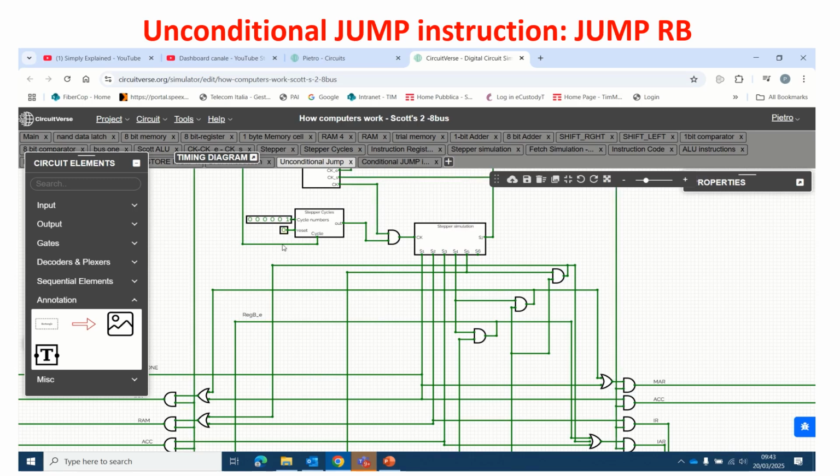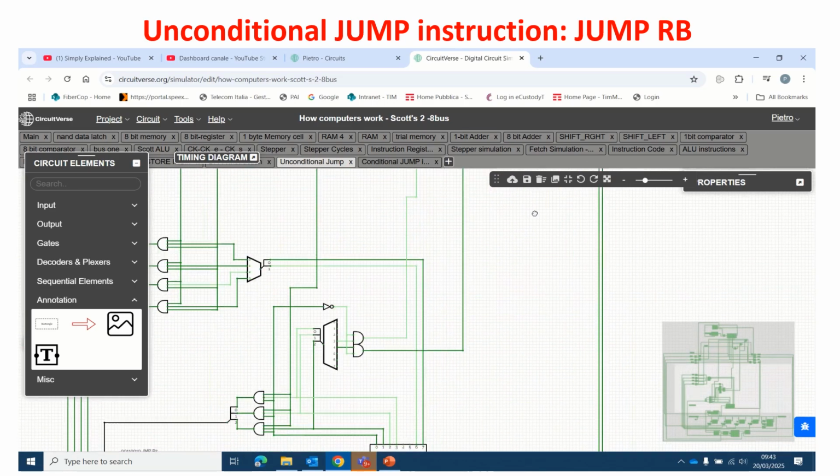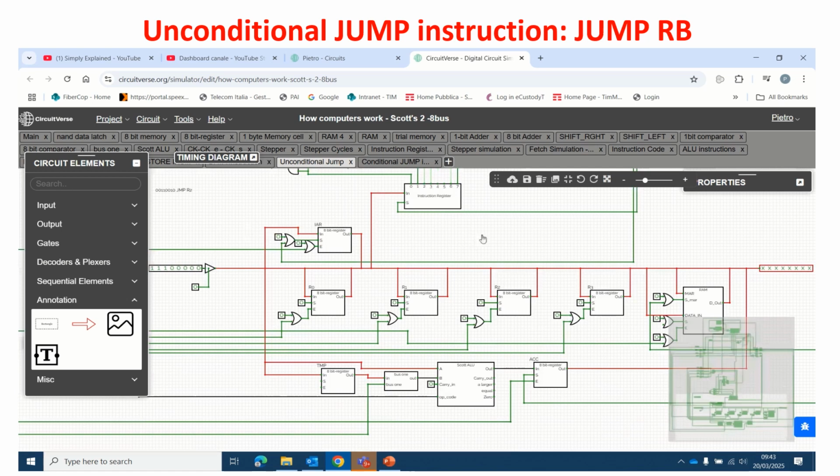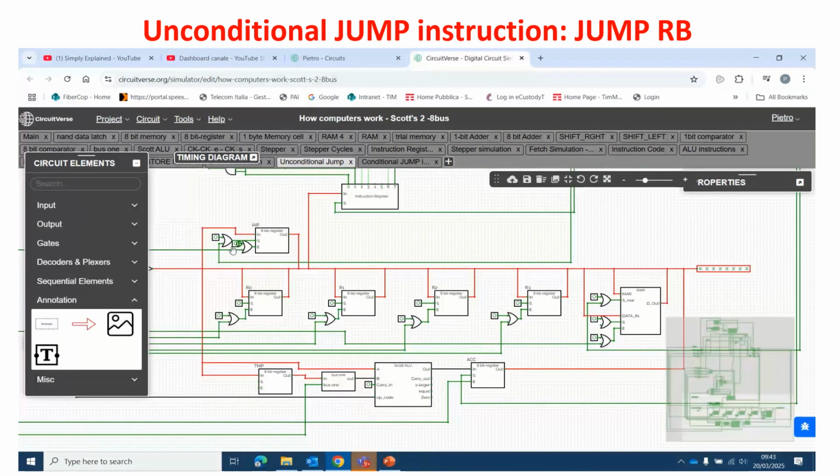So we perform just this instruction, and then the circuit stops. We give a pulse, and you see the step per cycle is running, and after the sixth step it stops. So we can check what there is inside the instruction address register, giving an enable pulse and putting the byte inside the instruction address register on the bus.